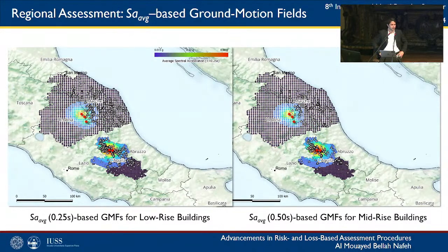Thank you for your comment and for your question. Yes, for sure, site conditions, VS30, water table, whatever you want, they influence greatly and significantly the generation of these ground motion fields. For the derivation of these ones, we used the microzonation study derived by Federico Mori et al. in 2021 that mapped the entire Italian peninsula in terms of VS30 values. Obviously those values were obtained using some sort of regression to map that component of VS30, and it can influence significantly the response of the ground motion model and its prediction of the estimated intensities.